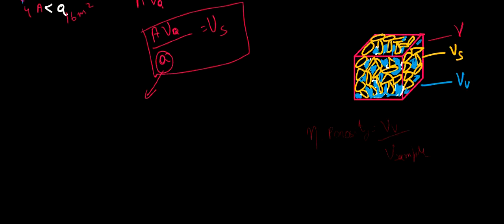Now look here. I have the porosity eta, which is known. If I multiply my eta with the total volume of soil sample, what will I obtain? We know that eta is nothing but Vv upon V sample, volume of void upon volume of sample, into volume of sample.